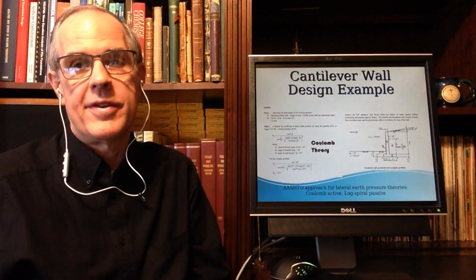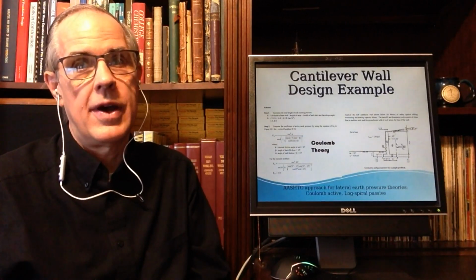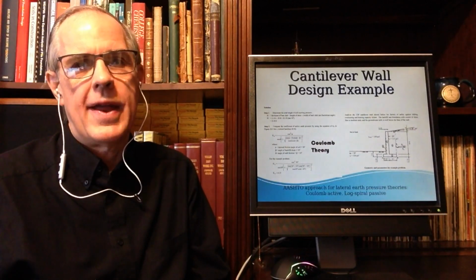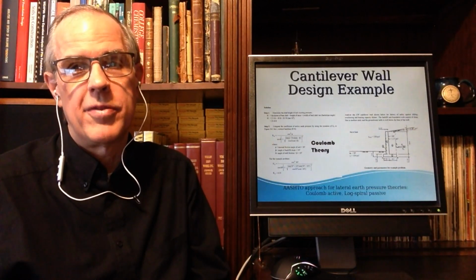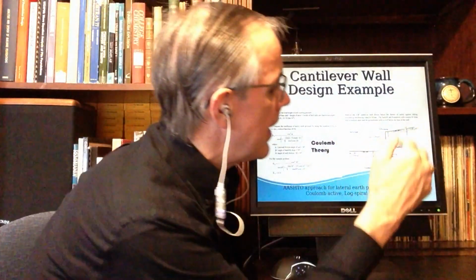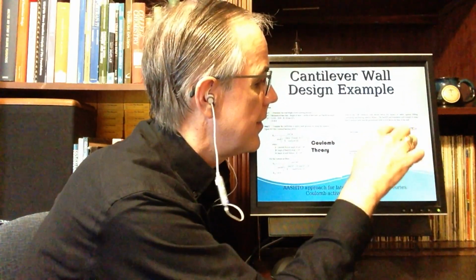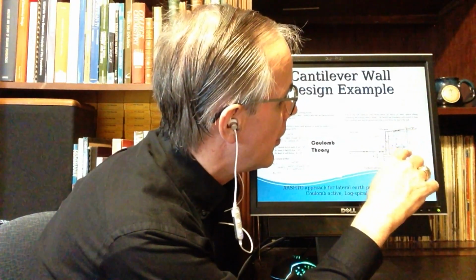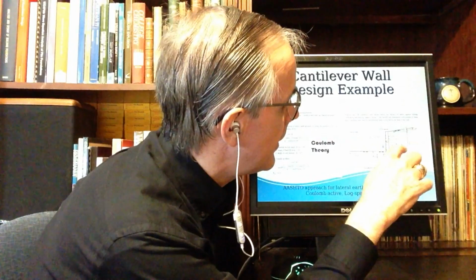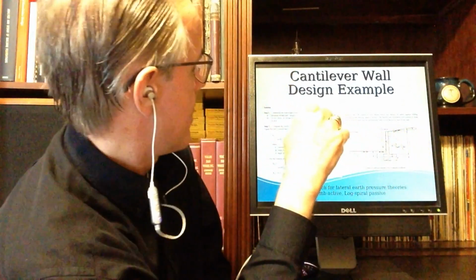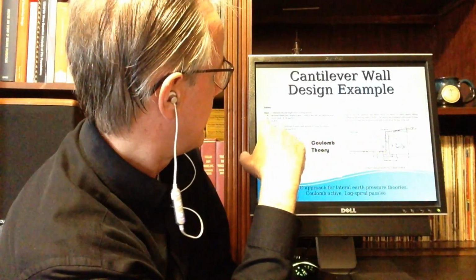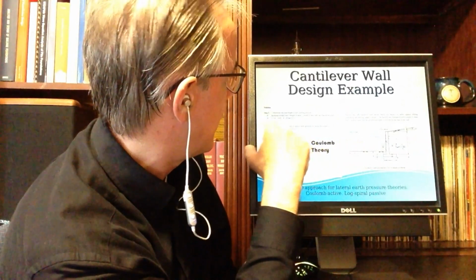In addition to the fact it doesn't weigh as much as concrete, although the difference is important, it's not an order of magnitude or anything like that: 120, 110, suppose 150. The other thing is that if you've got an upsloping backfill, you've got a longer distance here. You'll notice that you have two components over here, horizontal and vertical. We're going to get that at 10 degrees. We add that little thing as 21.8 feet.